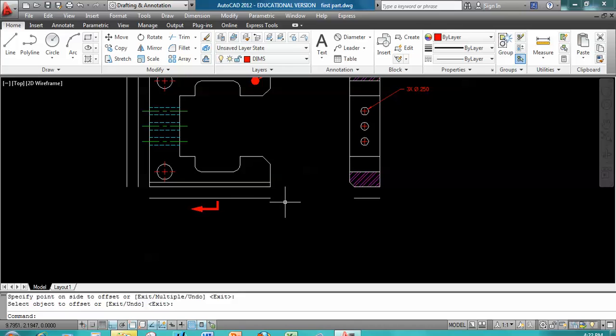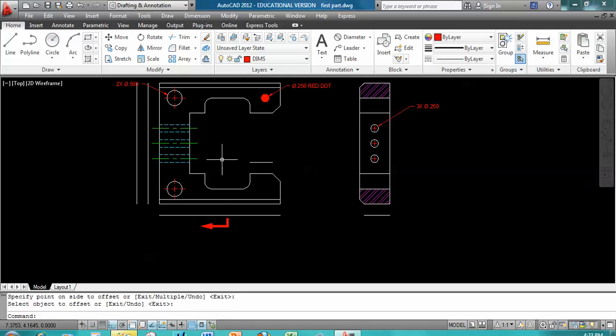Depending on the dimensions shown on the handout, we have to offset the lines 3/8 so we can place the dimension lines uniformly. So here, and then offset one more time 3/8 from here to here. Okay.